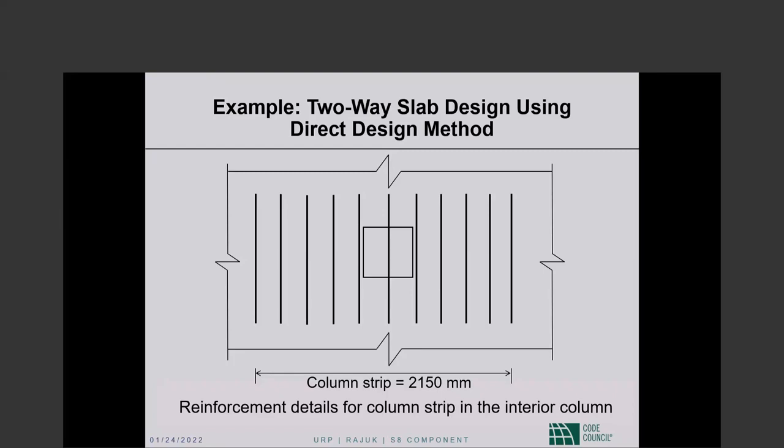Okay. So is it possible to design flat plate or slab on steel columns? Are there any design considerations specific to that? There actually is. There is so-called lift slab construction, and that requires shear heads.